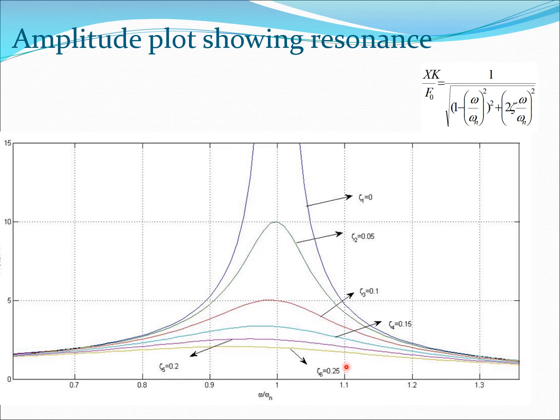So in many situations we not only have actual damping present in the system, for example, structural damping, material damping, and so on, but we may create some damping device or we may add some damping using some physics based thinking so that we essentially bring this curve down. So, a lot of vibration research and development work which goes on in companies is aimed at building dampers and trying to create this zeta in the system.